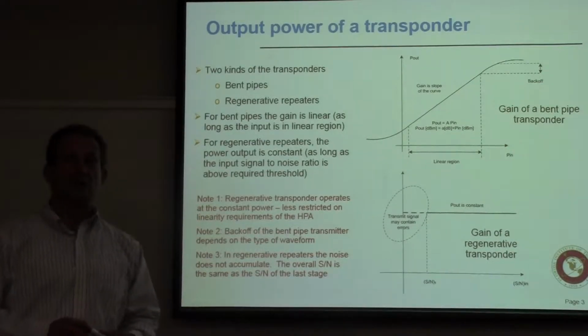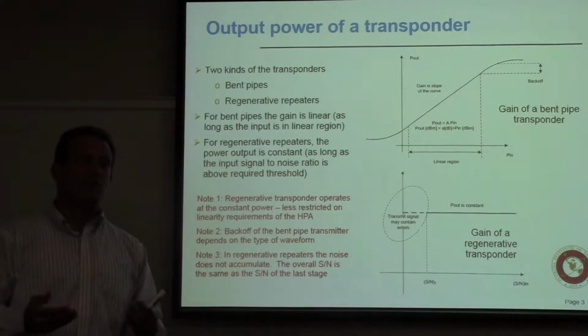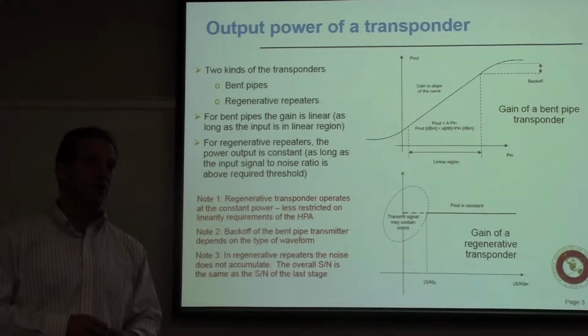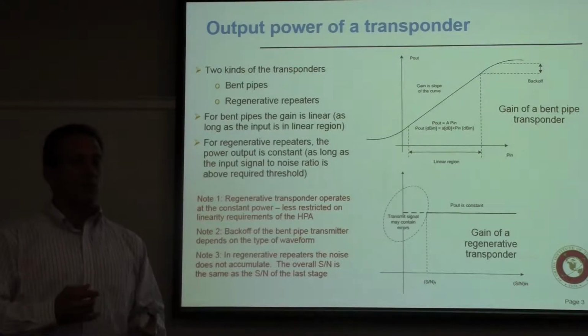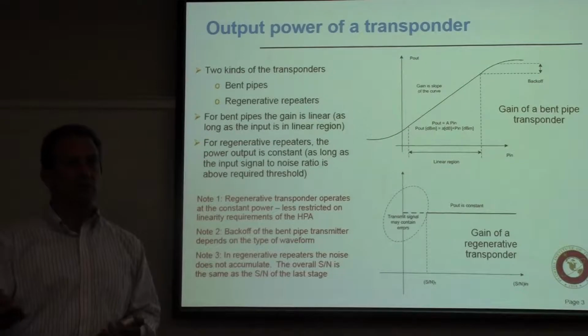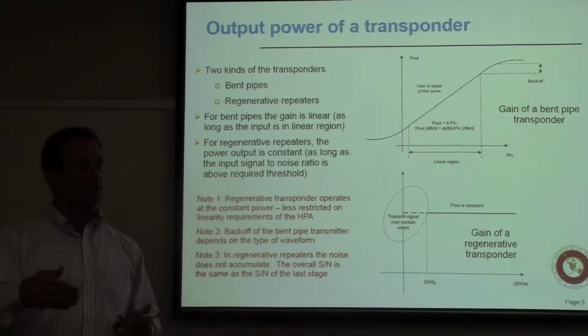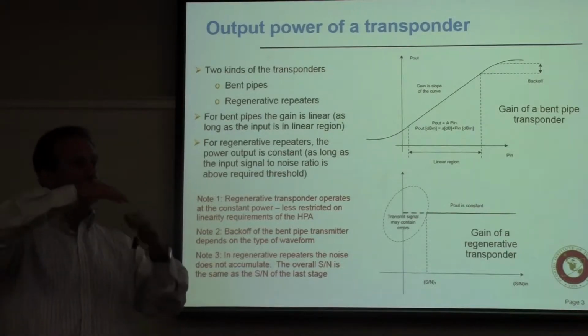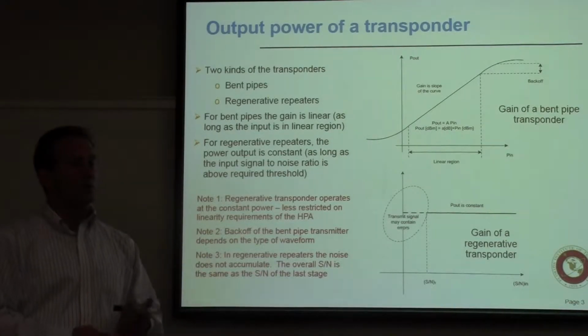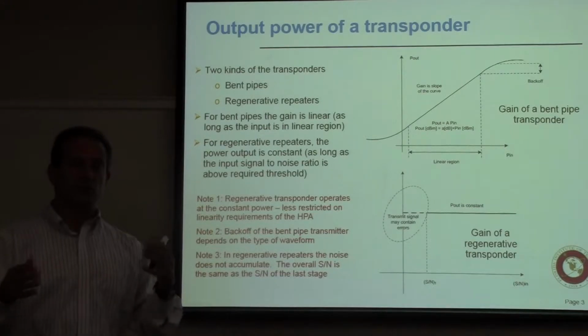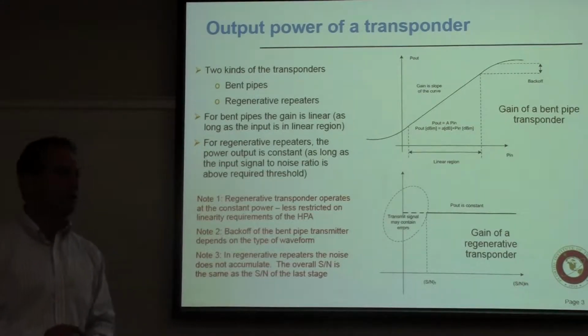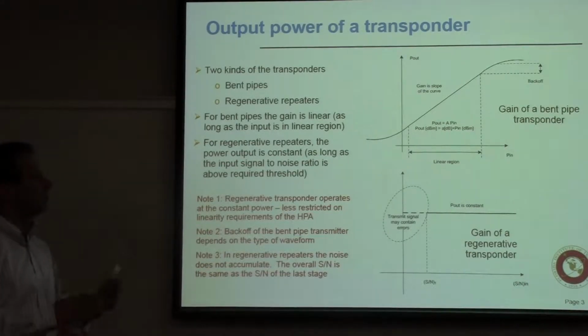What that means is we favor waveforms that have low peak to average power ratio. You will find a lot of satellite systems working with QPSK, even BPSK, PSK in general because it's constant power, and GMSK, the modulation schemes that maintain constant power, so that your peak to average power ratio is relatively small.